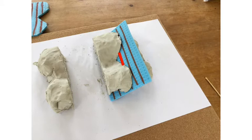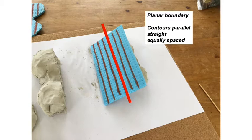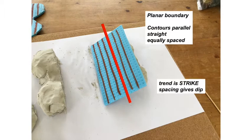So let's again strip off the landscape, and here is the extent of our blue sponge with our structure contour shown in the red bar running across there. So this is our illustration of the structure of the planar surface that is the top of our blue sponge. This is for a planar boundary, that surface is a plane. And for a planar geological surface, the top of our blue sponge in here, the contours are parallel and straight and equally spaced. The trend of these straight lines is the strike, and the spacing between different contours gives us an idea of the gradient of that surface, in other words, the dip.